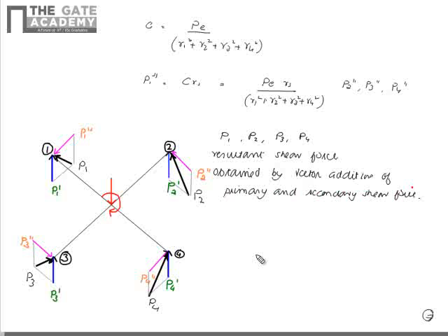And from this diagram itself, it is very clear that the resultant is maximum at bolt 2 and bolt 4. So, these two bolts will be subject to the maximum shear force. Once we design these two bolts to take the load, the other two bolts will automatically be able to take the load. So, thus we can do the bolted joint design for bolted joints which are subject to eccentric shear loading.